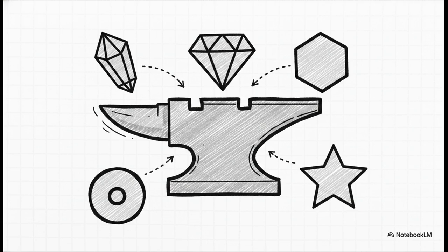If we look at the atomic makeup of that bolt, right beyond the base iron itself, we find these 5 fundamental elements mixing it up with the metal. We got carbon, silicon, manganese, phosphorus, and sulfur. Now, I really want you to frame these not as random impurities, but as the essential structural ingredients that we're going to reverse engineer today. Understanding how these 5 elements get into the iron and how they behave once they're actually in there is the absolute foundation of metallurgical engineering.